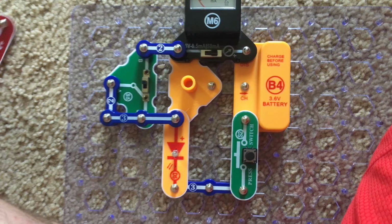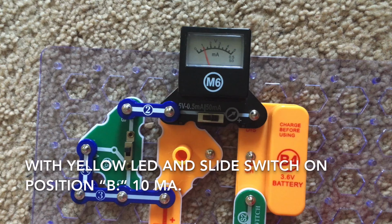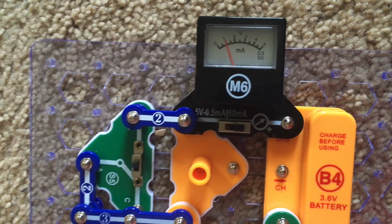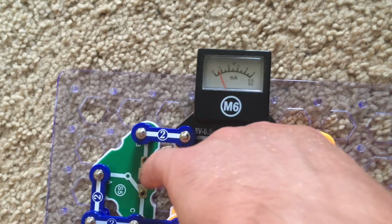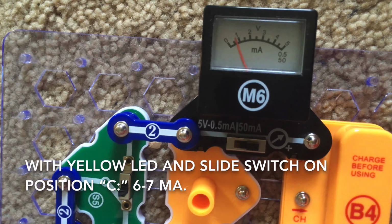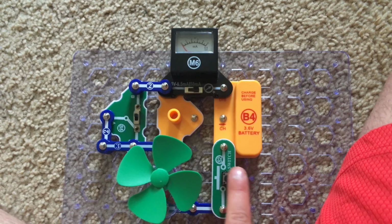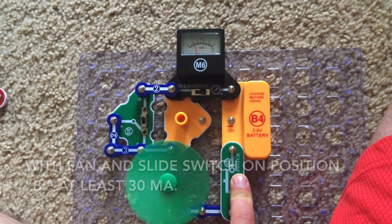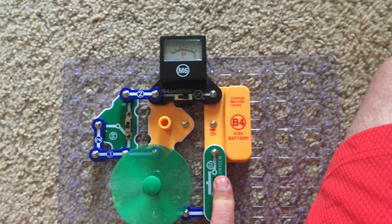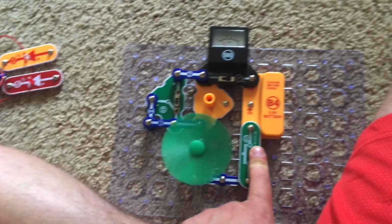Now we replace the red LED with the yellow one, and let's see how much current is used now. On the higher setting, 10 milliamps is used, and then on the lower setting, about 6 or 7 milliamps is used. Now we have the motor, and on the higher setting, at least 30 milliamps is recorded, and then on the lower setting, only just over 10 milliamps is recorded.